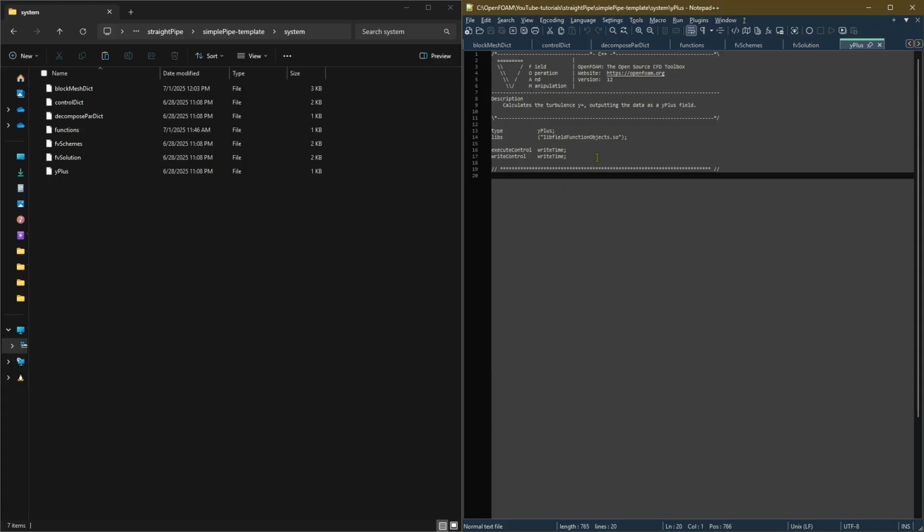This helps in explaining to my omega wall function where exactly my first cell layer is, and whether or not to use the viscous sublayer or to go ahead with the wall function route for calculating my turbulence.